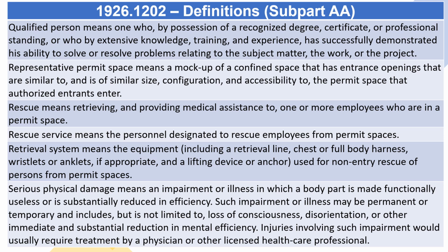Rescue means retrieving and providing medical assistance to one or more employees who are in a permit space. Rescue service means the personnel designated to rescue employees from permit spaces. Retrieval system means the equipment, including a retrieval line, chest or full body harness, wristlets or anklets, if appropriate, and a lifting device or anchor, used for non-entry rescue of persons from permit spaces.